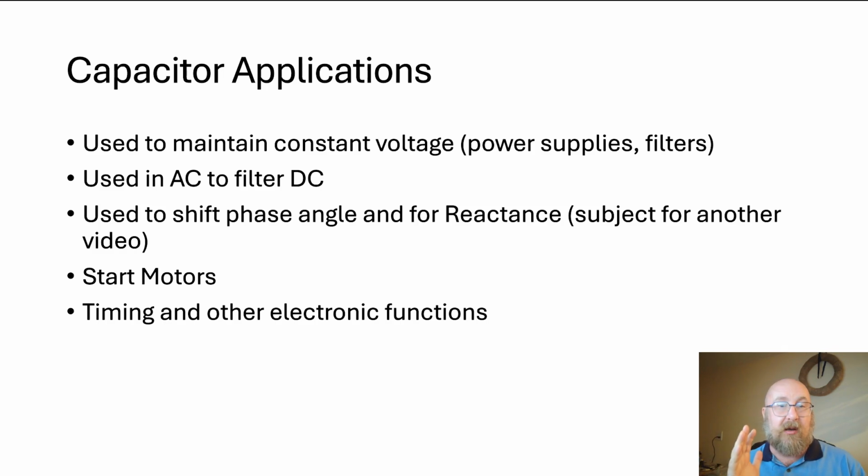They're used within the variable frequency drive that's going to drive the motor for our conveyor. There are even capacitors that will start AC motors if we use a different style of conveyor. We have some that use single-phase AC motors as opposed to three-phase motors. Those are going to be the motors that have that capacitor, and you may be wiring one up for those if you're using that style of conveyor.